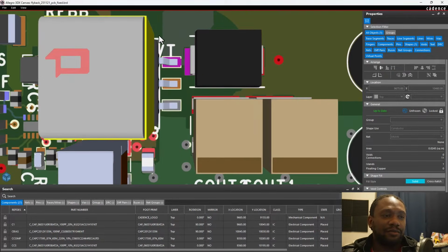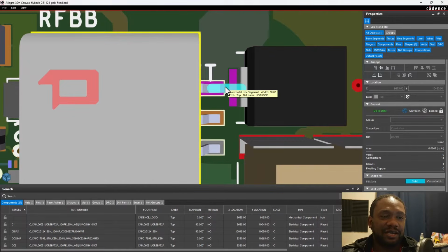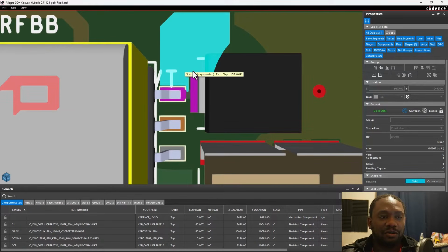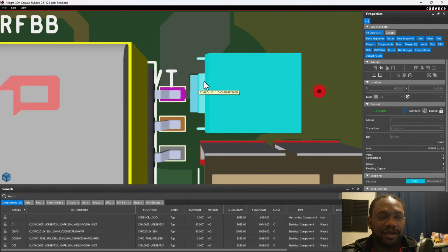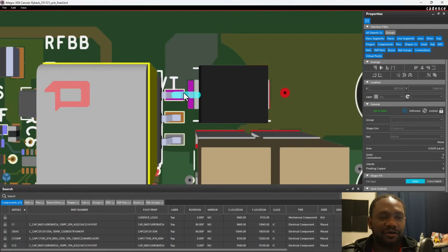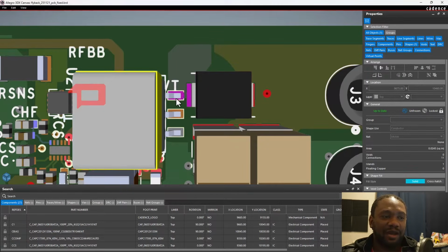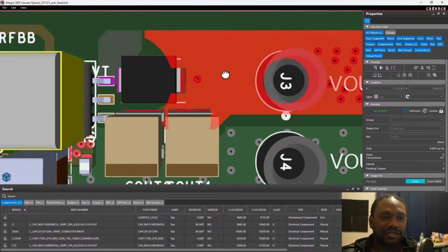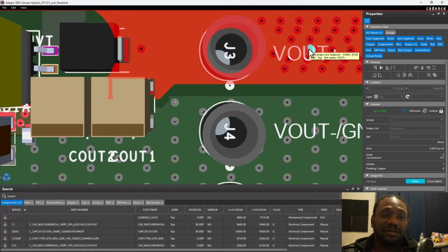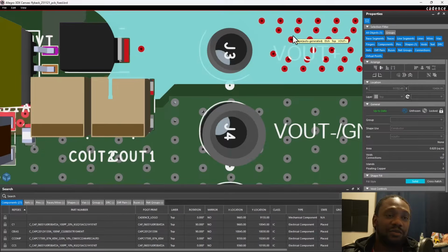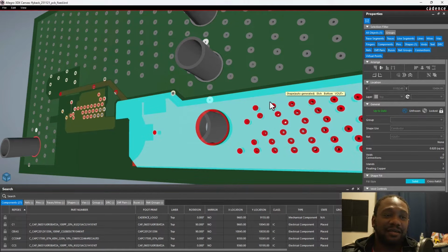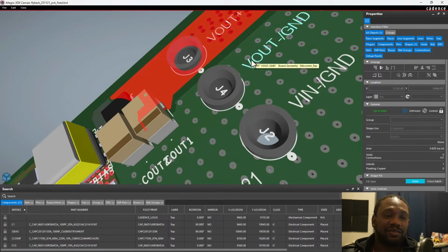Hot loop area number 2 is this secondary side of the transformer where I have copper pour going straight into my switching diode, and the diode is kissing the output pin on that transformer. Then V out is all of this copper right here, along with stitching vias to some more V out copper on the bottom of the PCB. Lowers that impedance or the inductance.